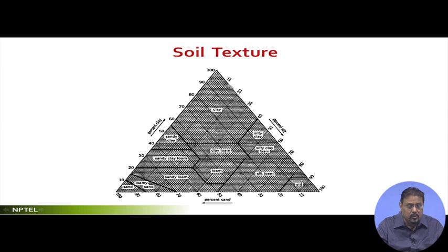If you go more into the clay zones, very interestingly, about 40% is silt, but we are still considering this portion of the soil as clay. That means this will be termed a clayey soil, which means we have more clay. If the quantum of clay is much greater in proportion, that soil becomes very, very weak in terms of stability and also in terms of vegetative capability.